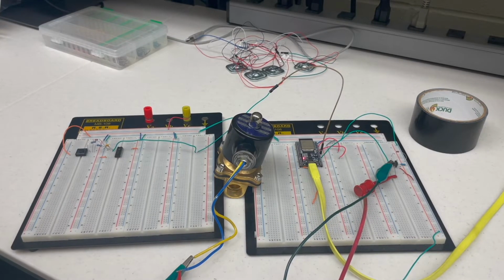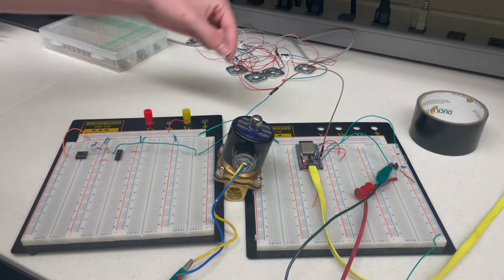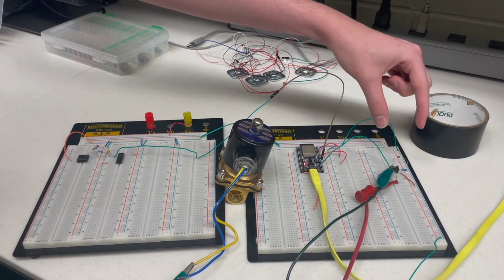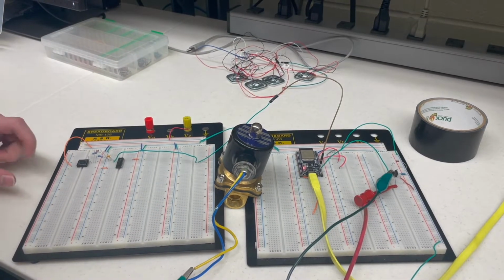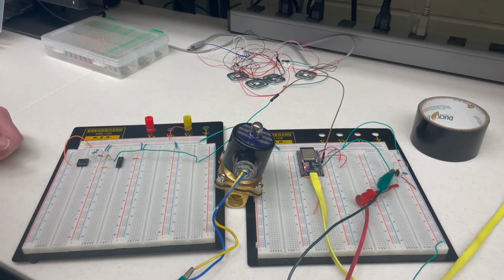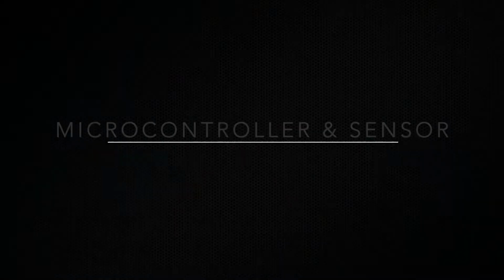Alright, so here we're going to demonstrate our solenoid dispensing. On the left side, we have our button with our debouncing circuit, and it's going over to our microcontroller through GPIO, which will then drive a control unit for the solenoid, which will open it. And here's an example of it working. Press the button, here open. Right now we have it set to open for 4 seconds. It closes, and then you're dispensed.